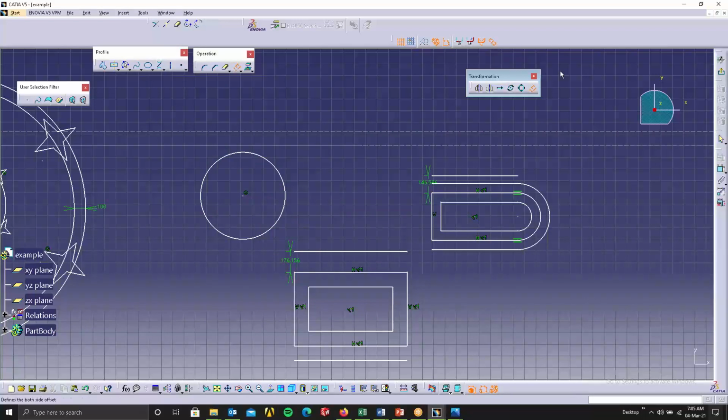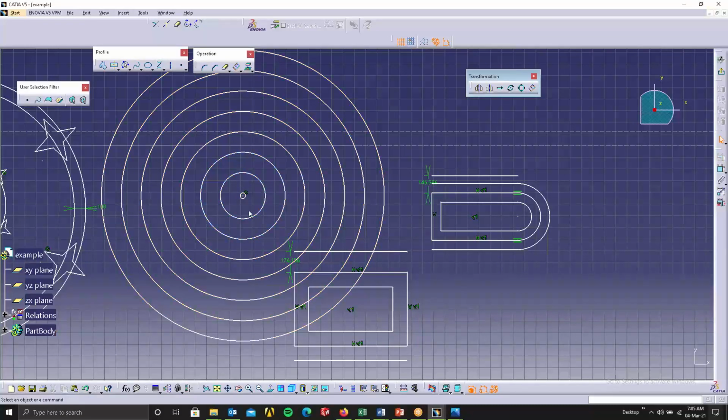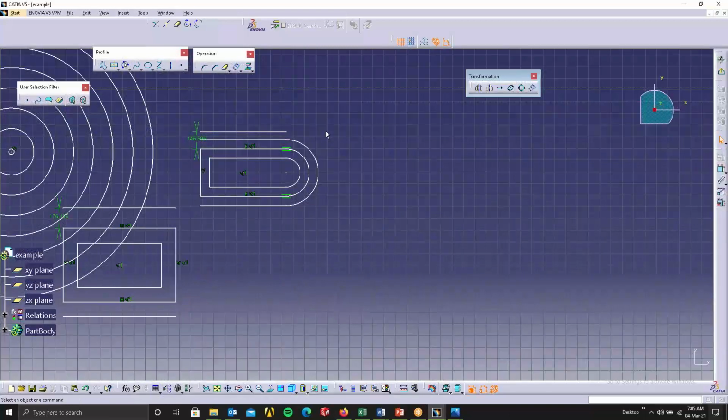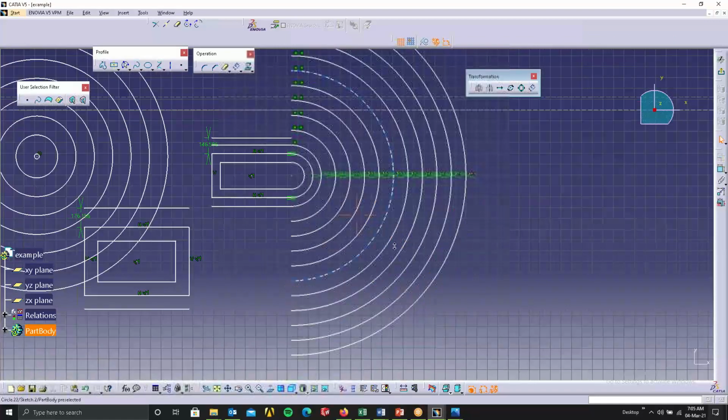So select this. Here one more option I can use is, I select the object. Here you see they have given offset distance, and here they have given the number of instances. How many copies you want. If I want, I can give 5 copies like this. See, 5 copies I can create. Any object, anything, I can create 5 copies. I'll turn this thing off. I'll just make normal propagation. I'll select this object. I'll give 5 or I'll give 10, whatever I want, and I'll create this propagation like this. Okay.